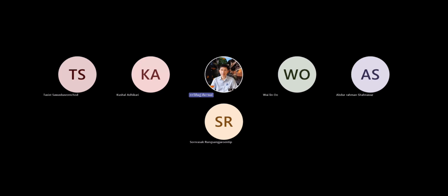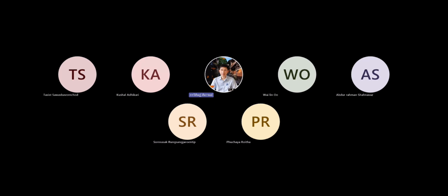First one is the moment of inertia, or the I symbol. This one we use to determine the capability of a section. Okay. The higher the moment of inertia is, the higher the capability of a section to resist bending moment will become. Okay, so we engineers have to.